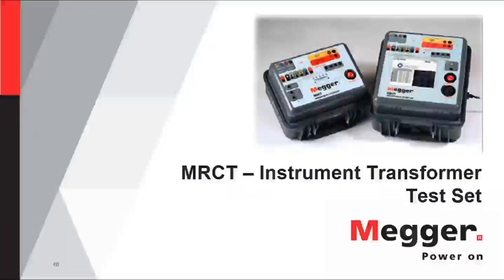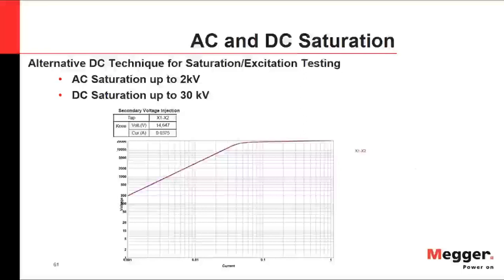Let's talk now about the MRCT, our Instrument Transformer Test Set by Megger. In this device, we have AC and DC saturation. This alternative DC technique for saturation excitation testing, as it has been discussed during this presentation, will allow us to do AC saturation all the way up to 2 kV and DC saturation all the way up to 30 kV. As you can see in this example, this is a CT tested in the field with a saturation knee point at about 20,000 volts.